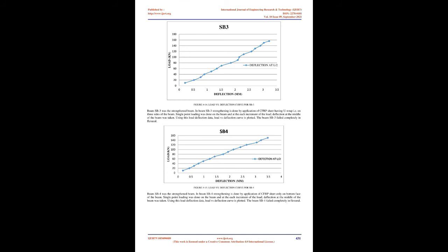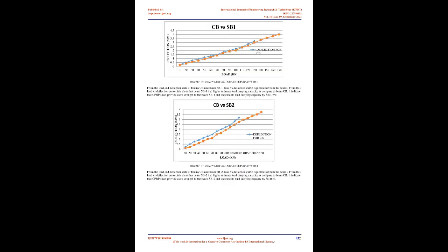Failure modes and crack patterns. The following failure modes are investigated for a CFRP strengthened section. Crushing of concrete in compression before yielding of the reinforcing steel. Yielding of the steel in tension followed by concrete crushing. Debonding of the FRP from the concrete substrate, FRP debonding. The CFRP strengthened beams and the control beam are tested to find out their ultimate load carrying capacity. It is found that all failed in flexure.